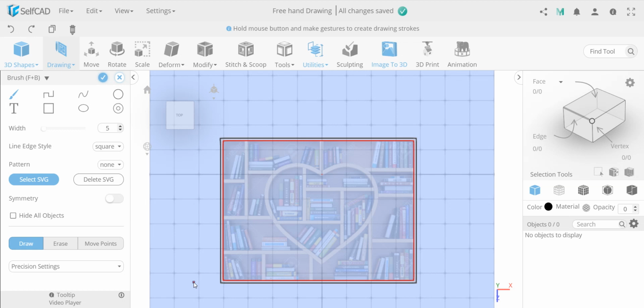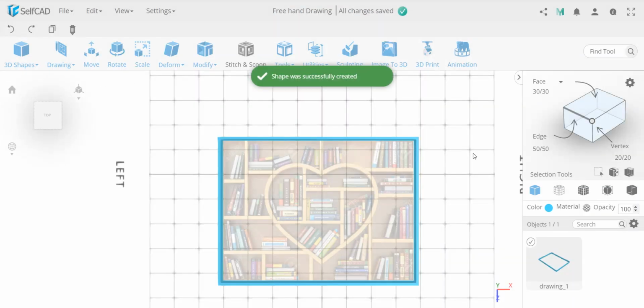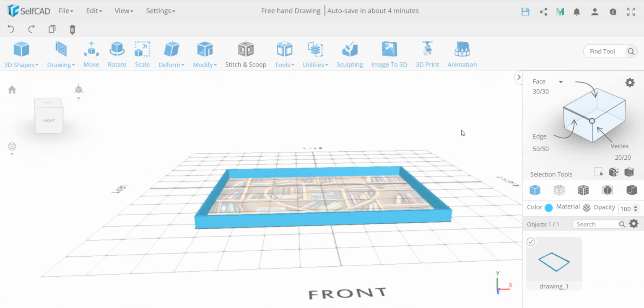But nevertheless, once I have this, you see I have the box, which is the outside, and then you have the inside, which is going to be the hole. If I have the fill settings to fill the holes, this will be one solid. It will create a cube. But if I have this, it will create just the frame. So I'm going to finalize this, and I'll come back to show you how we can use it later, just to get familiar with how this will look. So if you finalize this, you see we didn't create a hole, we created only this box.